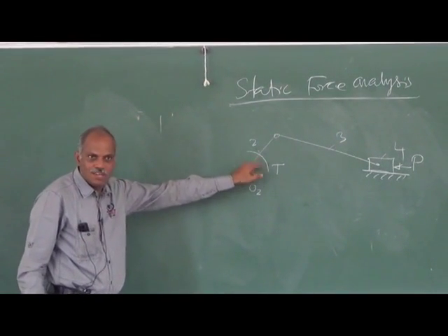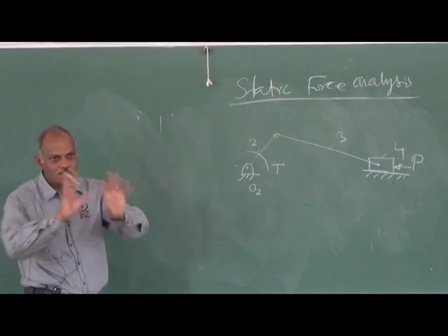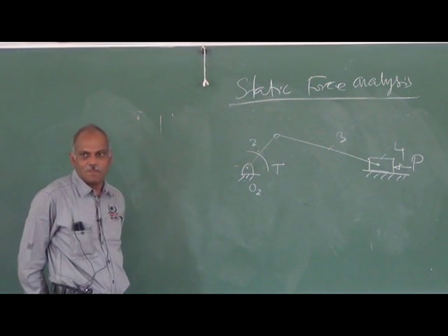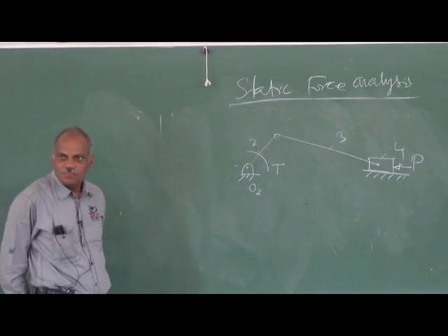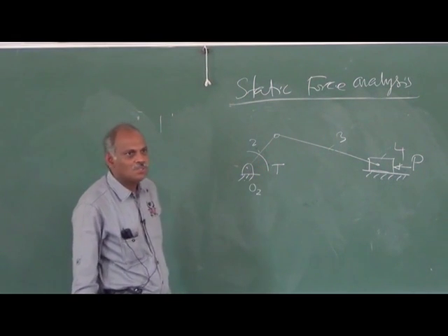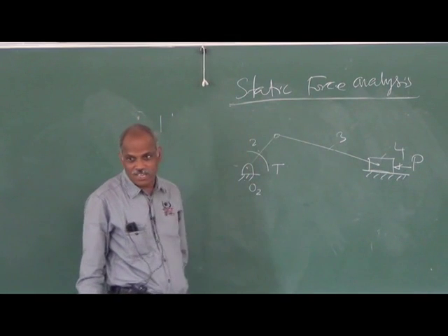Now, the question is, when a force P is applied on this, what is the holding torque I should give on link 2 so that the system will be in equilibrium? In the sense it will be in static equilibrium. Okay, so that is the question. How will you find out the holding torque? For that you have to do the analysis called the static force analysis.